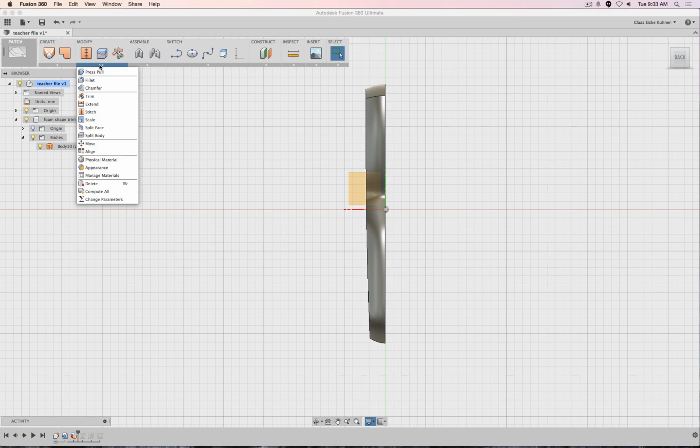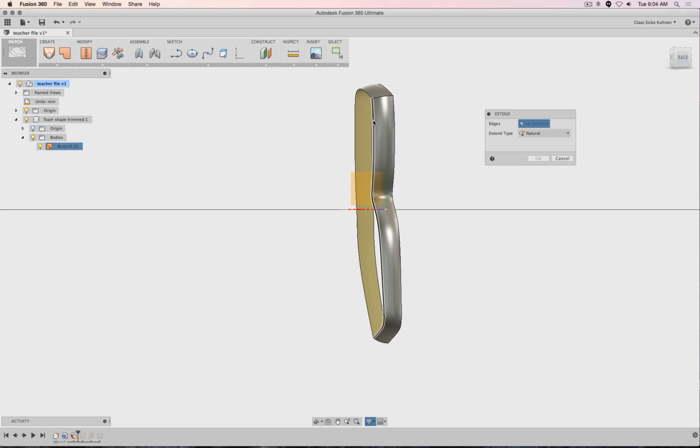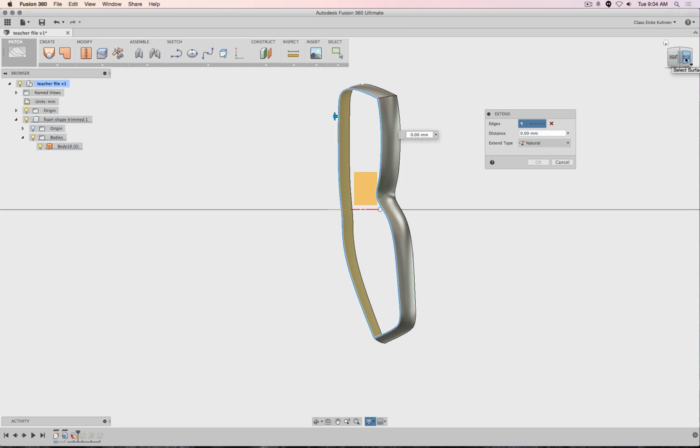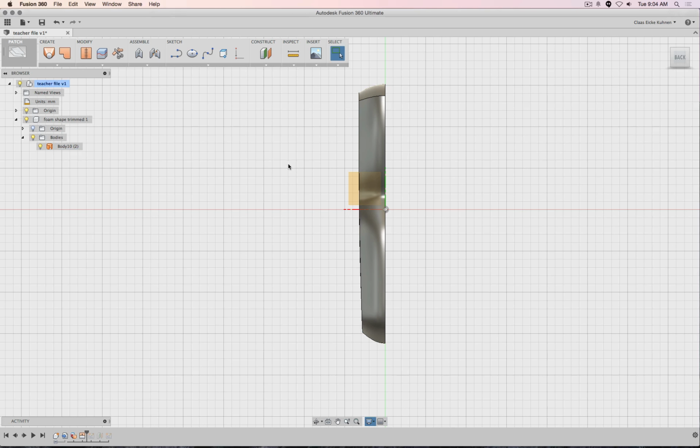I go to extend there, because when I delete those faces, then I can extend actually those edges out. And for example, extend this maybe 5 millimeters. I think that might be enough. Let's take a look. Yeah, so here's my construction plane, so that's all good. Perfect.